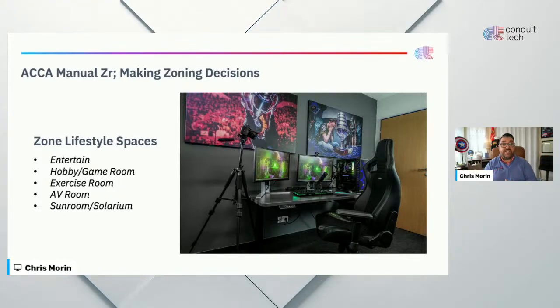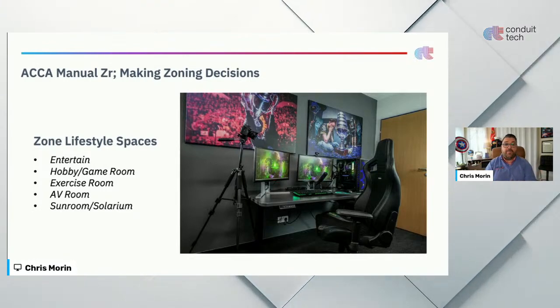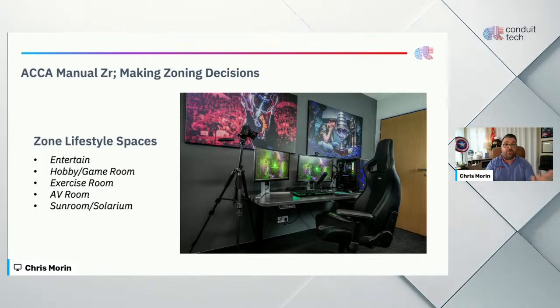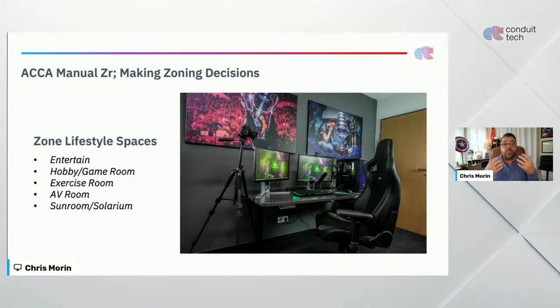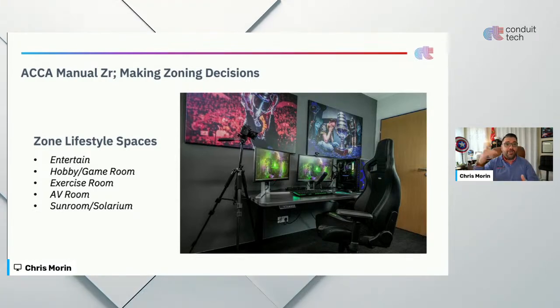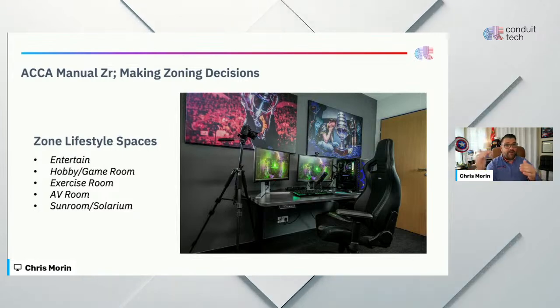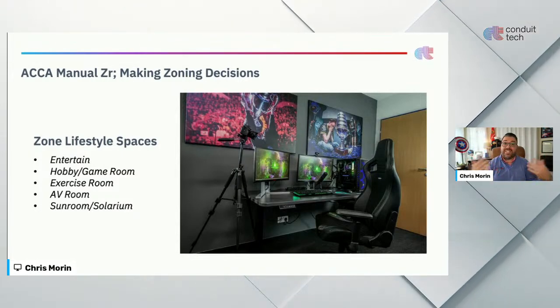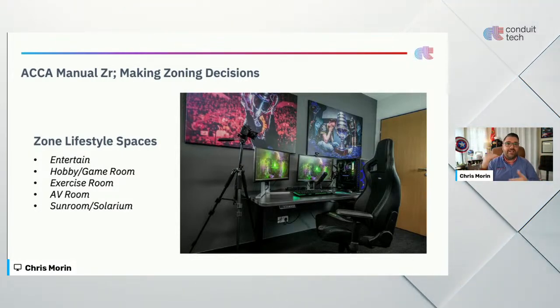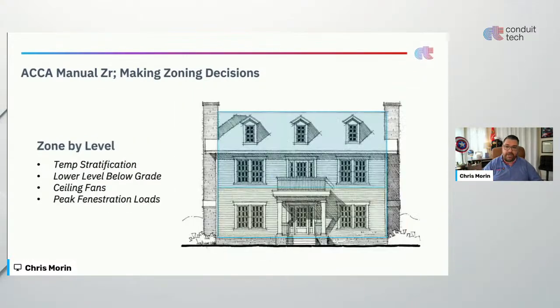May not be the case in every home. You may not have to zone that off based on the way they're living. But if you want the new homeowner to be comfortable, it's their opportunity to address that problem, particularly when you're replacing a system, right? This is what we're talking about. You do the load calc. Now we have to address how we're going to zone it out before we select all of the equipment for it, right? Manual ZR comes before equipment selection. All right. So enough beating on that. Those are some obvious things to zone out.